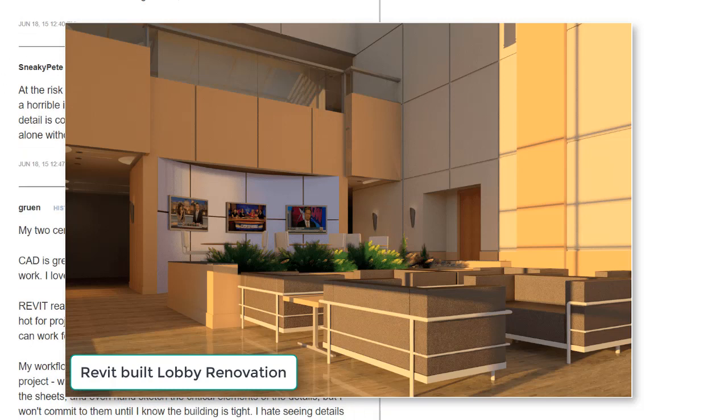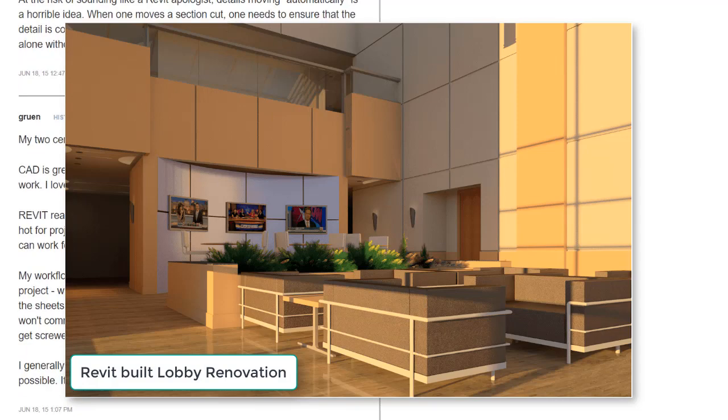This happens when you're inputting some of your annotation, whether this is in the viewport or on the sheet. Some things don't always line up. Like Revit had this weird thing to where you can't always type in a viewport, so you end up typing on the sheet. But if you move that section cut, then your details and your annotations are no longer correct.